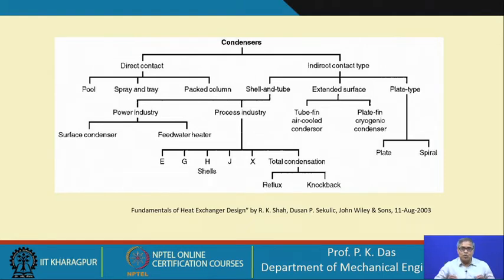Now, this is important that water will be passing through the tube side and steam will be passing over the tube. Again I will try to show you different diagrams, photographs etc., taken from the net, so that you can get a good idea how the process takes place. And this condenser where condensation is taking place on the outer surface of the coolant tubes is called a surface condenser. So, specifically this name is used for steam power plant condensers, but any type of condenser where condensation is taking place outside the tube, then we call it a surface condenser.